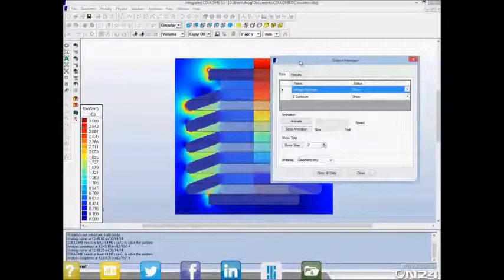But if you turn this voltage on and leave it for several hours, days, weeks, then it is actually the conductivity solution that dominates. And when you're looking at something like potential device failure, you really need to consider both. You need to consider whether it will withstand the field distribution when you first turn it on, as well as the field distribution over the much longer term.